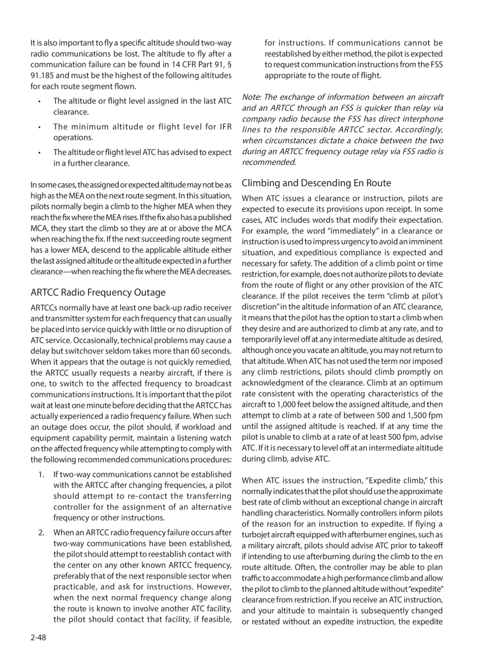When ATC issues a clearance or instruction, pilots are expected to execute its provisions upon receipt. In some cases, ATC includes words that modify their expectation. For example, the word immediately in a clearance or instruction is used to impress urgency to avoid an imminent situation, and expeditious compliance is expected and necessary for safety. The addition of a climb point or time restriction, for example, does not authorize pilots to deviate from the route of flight or any other provision of the ATC clearance.